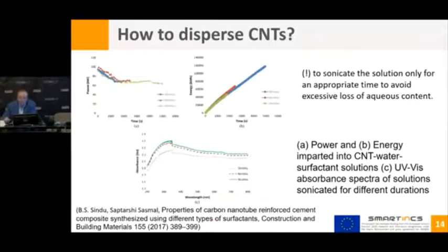Then, at that point, one important parameter is the time we apply the sonication. If the time during which we sonicate the system is too short, of course the dispersion won't be optimized. And at the same time, if the treatment is too long, this is a waste of time, and a waste of money.